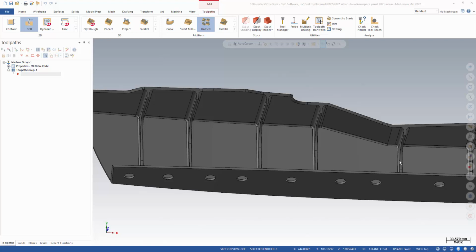New to Mastercam 2022 is a toolpath that I'm very excited to introduce to you. It's called the Unified Multi-Axis Toolpath. You'll find it right up here, or of course in the right-click menu of the Ops Manager. What this toolpath does is consolidate all of the various options that we had for free-form toolpath creation, such as parallel, morph, along curve, project curves, and add some new functionality as well, such as flow, a geodesic algorithm, and we could leverage the geodesic with an infinite number of input chains or just automatically resolving the boundaries, all sorts of cool things.